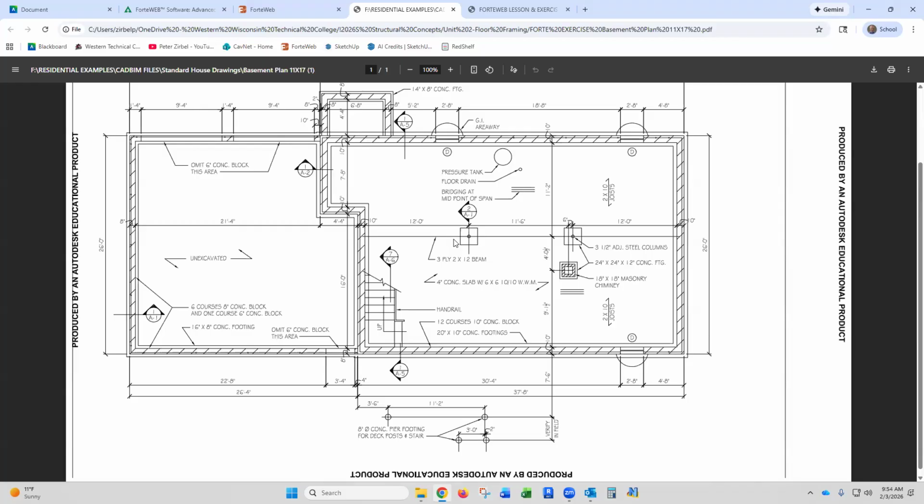We're going to try to minimize the depth. So when I say minimize the depth, that beam is hanging down from the floor. I'll just draw right over here. So our floor joists are going to be running across. I've got a dropped beam and it's going to be a 2-ply, 1 3/4. And when I say minimize depth, I don't want to hit my head on the beam as I'm walking around, right? So I'm going to try to minimize that depth.